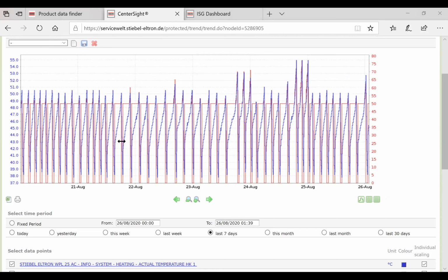this way. This is just a showroom one, so we've got it running in a fairly crude manner. As you can see, when it's starting up, it goes straight to 50 Hertz. We can give our heat pumps, which I'll go into more in the advanced commissioning, a target to hit when it starts. So instead of it starting very, very low and ramping all the way up from the bottom, we can say, we know our heating system is this big, start at that, and then it can work its way from there.